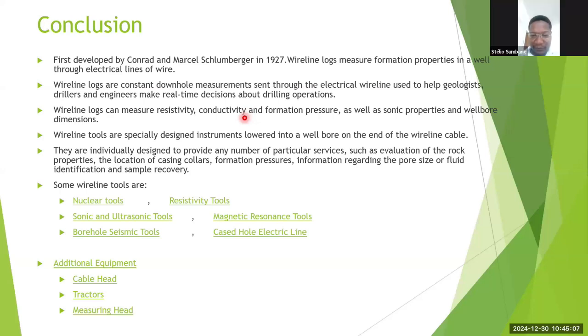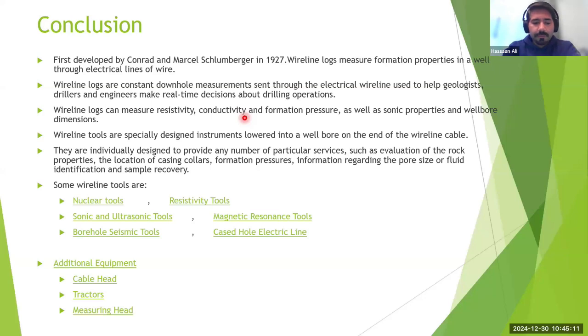Sorry. Thank you, Stelio. So to determine that, the different cable sizes are very specific to the wireline companies as well. Different companies will have different wireline cable sizes. Essentially, the cable size is determined by two big factors. One of them is the safe working load of the cable. That means how much weight are you going to hang at the end of that cable, and how deep it needs to go, right?